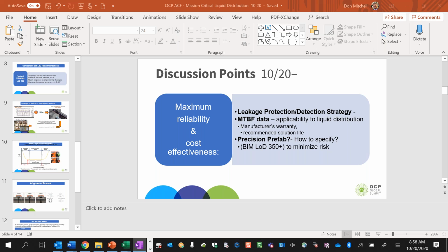What size pipe are you dealing with on these shipped and packed in nitrogen? So those were in 2 to 3 inch category. Those are the coils, cooling coils were manifolded. Cooling coils had a capacity of about 500 kilowatts a coil and ran 150 GPM through them.